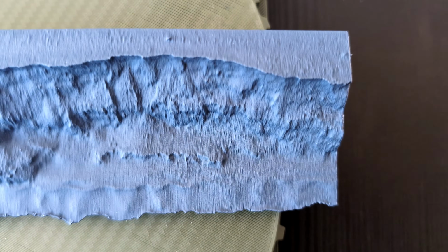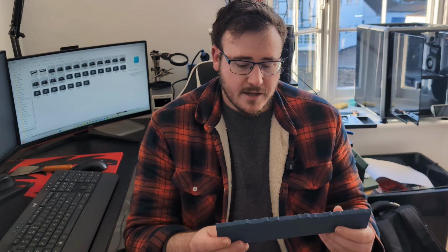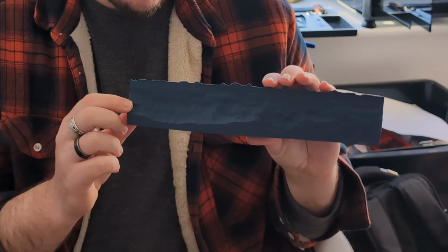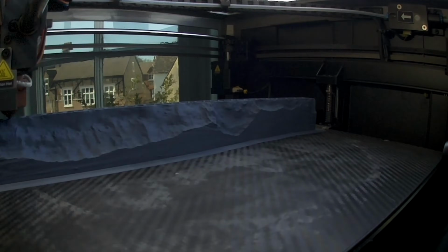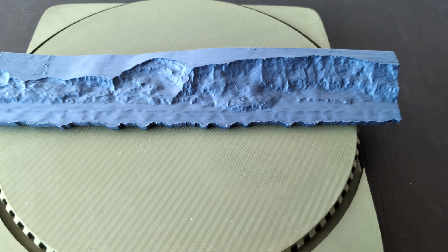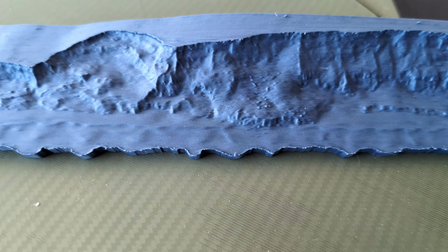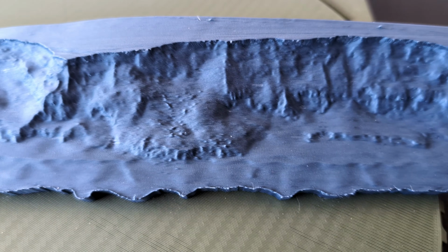And once we had printed it and I'd looked at it, it dawned upon me that, going through all the Boolean operations that we did on the sides and the back, we actually could have just printed it in this orientation, and built it up layer like that. Does it look better? I think it looks a little bit better. When you're looking at it head on, the layer lines are less distinct.